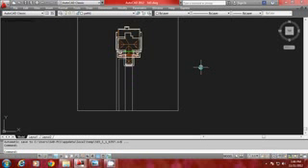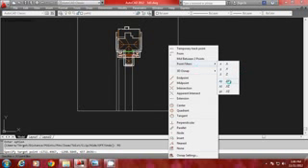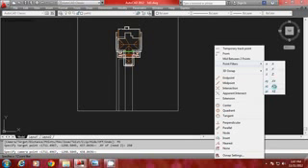So, in this model, I'll give, say, dview command, and I'll select the objects to be visualized. And I'll go to points option and I'll select the target and camera points just as we have done before using point filters. So I'll go to shift right click, I'll go to point filters and I'll select .xy off. I'll pick a point over here and I'll give Z as 250 units, and it'll ask me for the camera. I'll again go to point filters and I'll select .xy off.